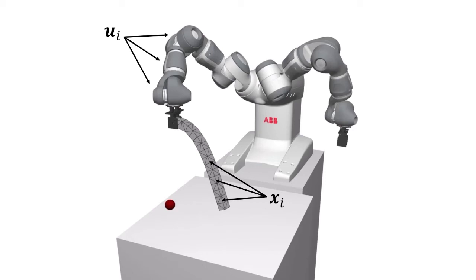The robot is modeled using its kinematic chain and its joint angles. All angles are stacked into the vector u_i, which describes the controls applied to the system at step i. The individual targets of all conducted experiments can be incorporated by including objectives into the overall optimization problem in form of quadratic penalties. These penalties match a specific mesh node to a target in world coordinates at the given trajectory step.